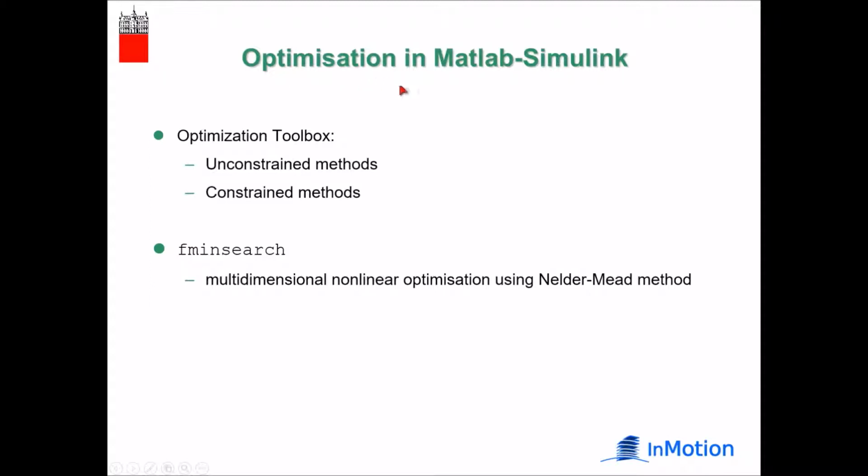Let's say some words about the optimization in MATLAB Simulink environment. We use optimization toolbox. In this toolbox there are many unconstrained methods and constrained methods, and in our example we will demonstrate the fminsearch function. This is multidimensional nonlinear optimization using Nelder-Mead method.